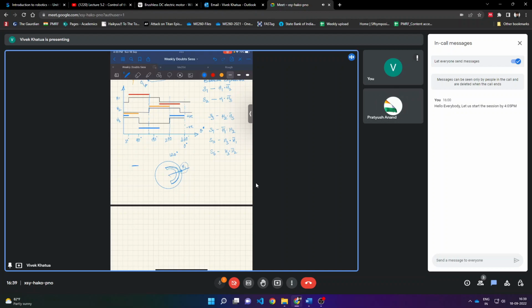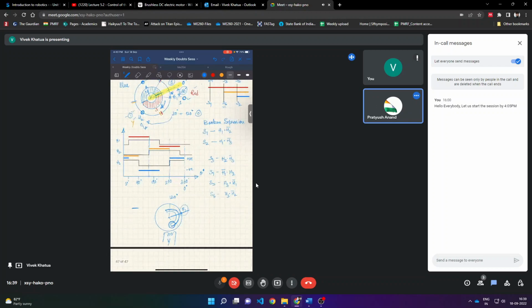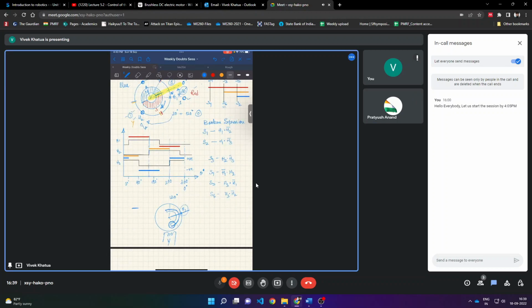And here you can see that the moment it was going there, this part of the north pole was interfering with the Y coil. That is where the EMF was generating. From this point the induced EMF in Y was increasing. I have given this notation: you can see the red I have given here means this is positive, this is negative. Below the Hall sensor, anything I have given is negative. And for H2, this is positive, this is negative.